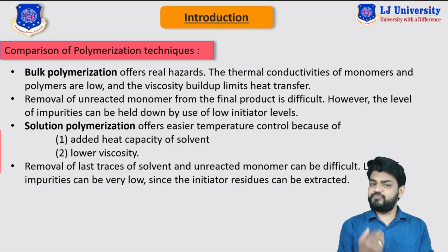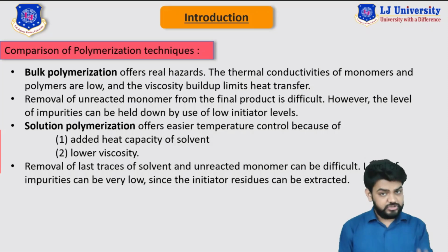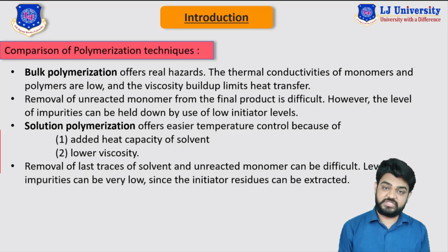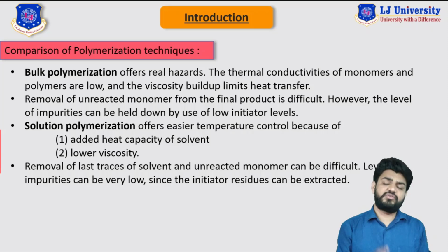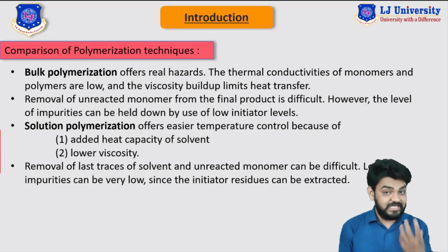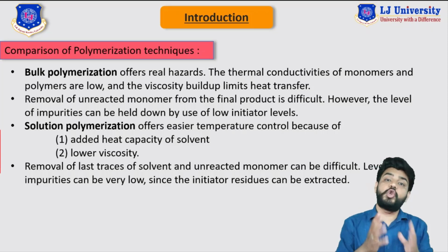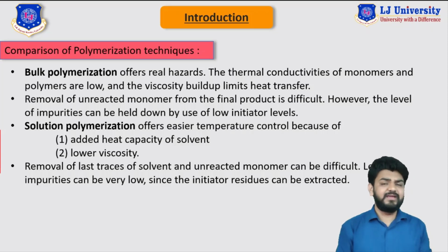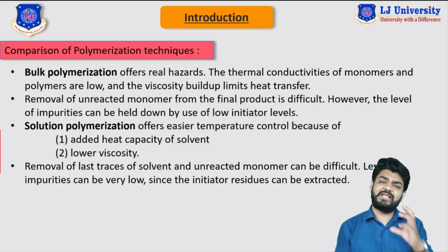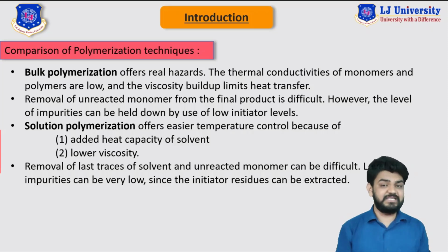But in the case of solution polymerization, the produced product is also in the liquid state. This is why these viscosity effects are not that significant in the case of solution polymerization, and that can lead to better heat transfer and mass transfer operations. So there are basically two reasons why this thermal control is very easy in the case of solution polymerization.